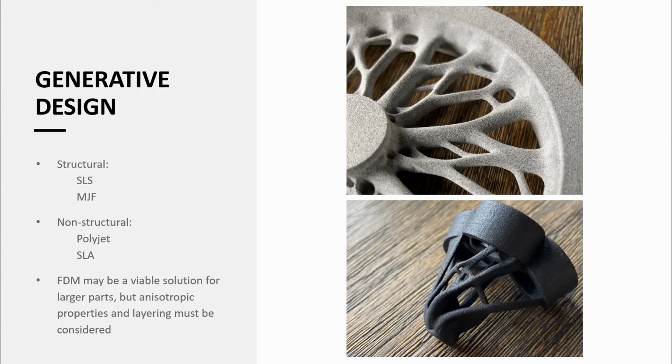FDM is also capable of printing generatively designed components, but may suffer from layering or anisotropic properties. As many of you know, generative design only accounts for isotropic materials, and so this is an important consideration for whether or not FDM would be a good choice for the parts. FDM might be a good choice for generative components that are very large that would not be able to fit on one of the other printers.